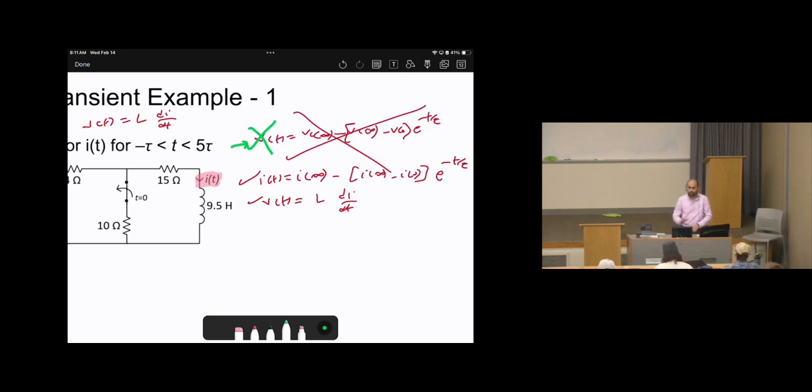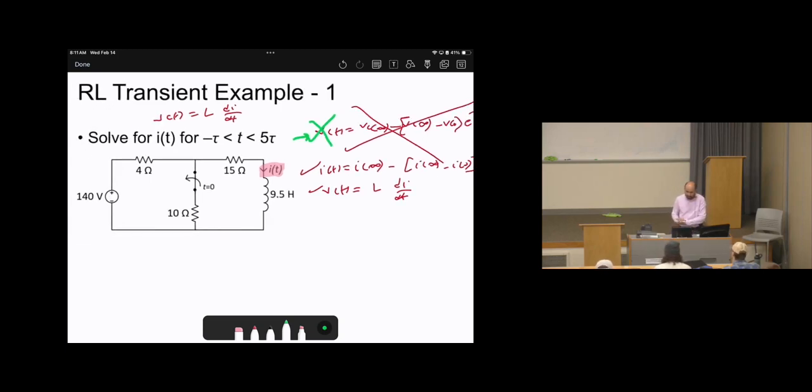It depends. Are you dealing with inductor or capacitor? We're dealing with inductors. Then that's the formula that's associated with it. Now, how to calculate the currents? By looking at the circuit, the first thing, there is a switch, then it is transient. So it's not DC. We cannot say the inductor is short circuit and do it. So let's do the transient problem. And there is, in Henry, the inductor is in Henry, therefore it is RL circuit. Then we apply this formula.